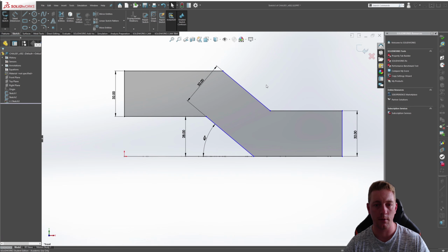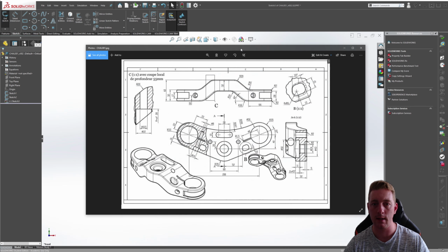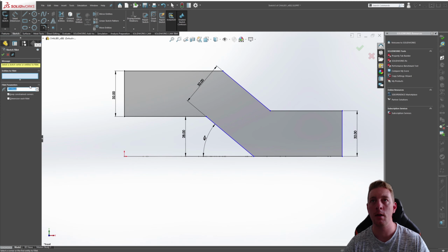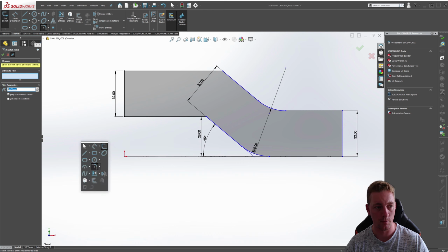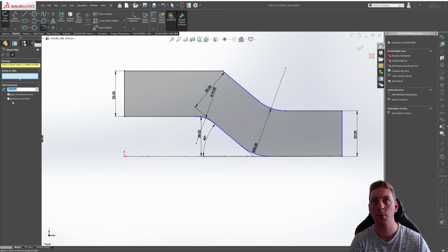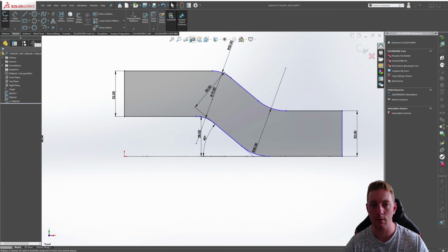So we might go ahead and start adding those filleted edges in first anyway. And we can just go through. We know we have one of 30 at this point. We also have a 30 at this point. And then we have a 19 here. And then the last one, which is the top edge, is a 20. And we have finished the fillets.